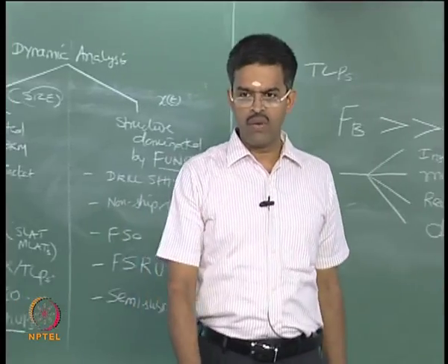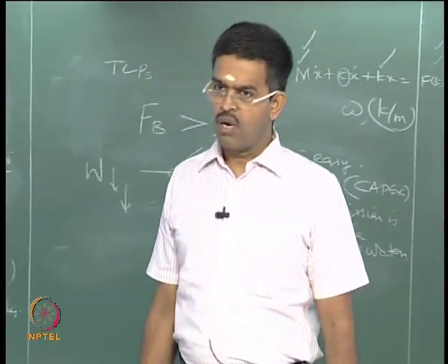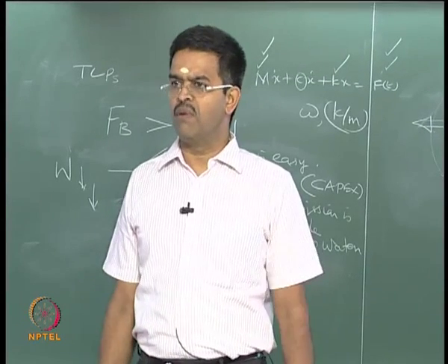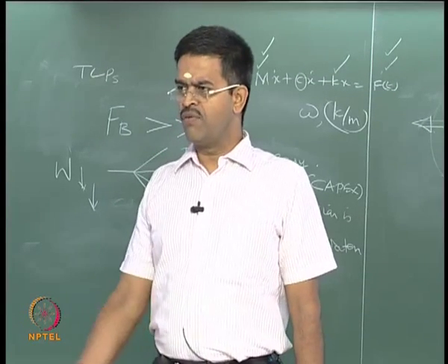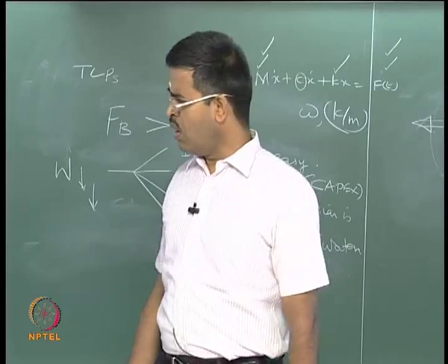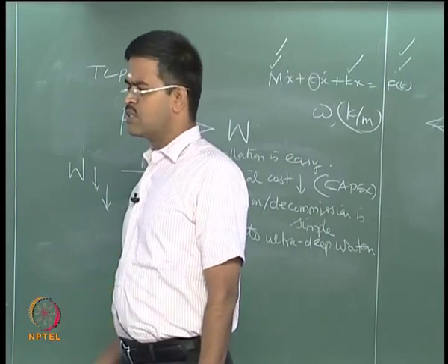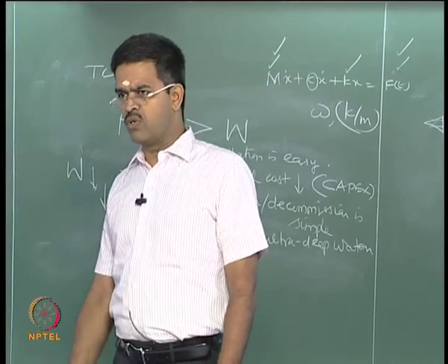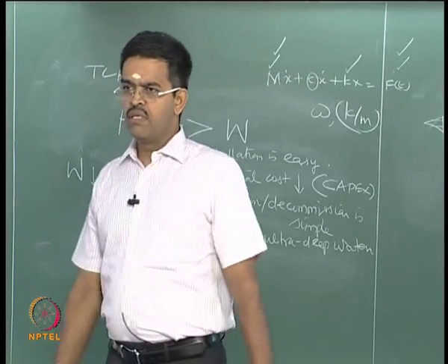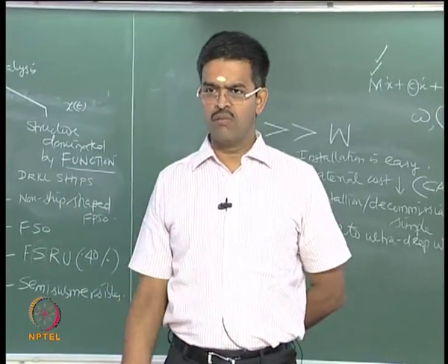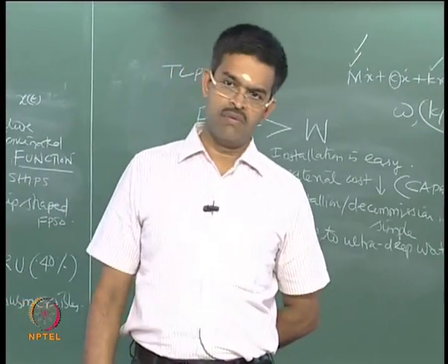That is how we will, when we have a fixed structure or a member fixed to the support, forces become important, because then response will be very minimum. For example, a gravity based structure or a fixed jacket structure. So when you have got a structural system or a member whose dimensions are related to the flow field and the boundary conditions impose fixity on the member, then forces on the member, stresses on the member become very important, therefore fatigue plays a very important role.